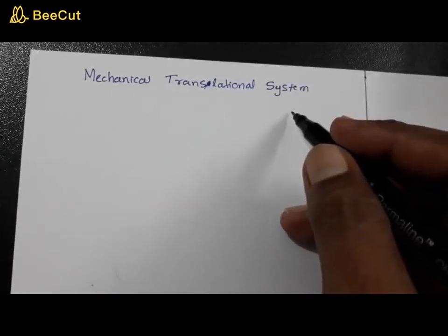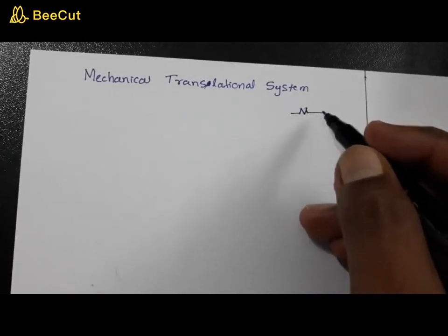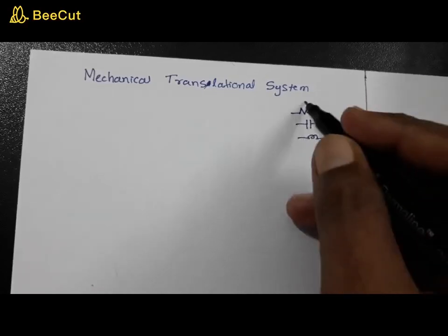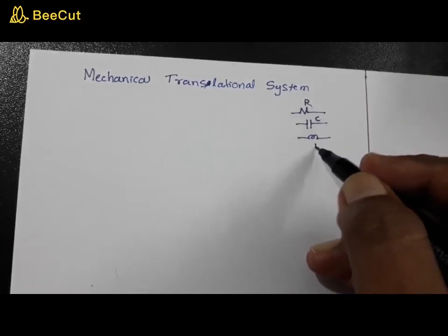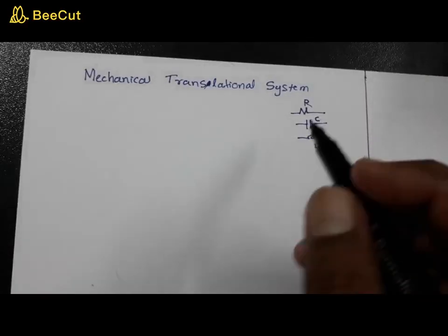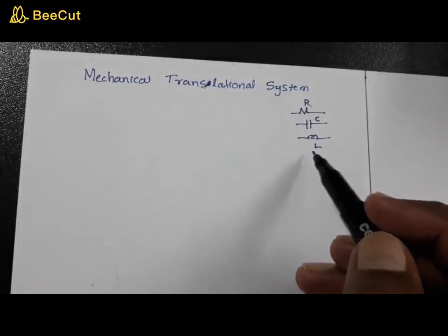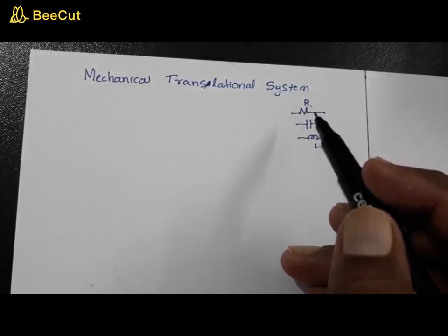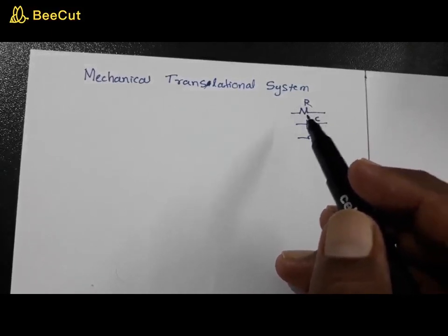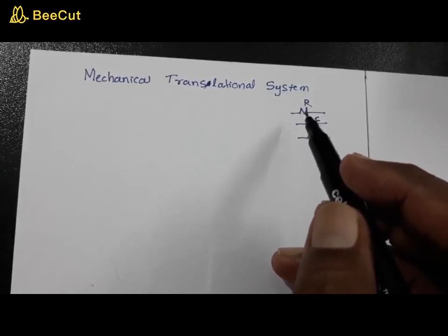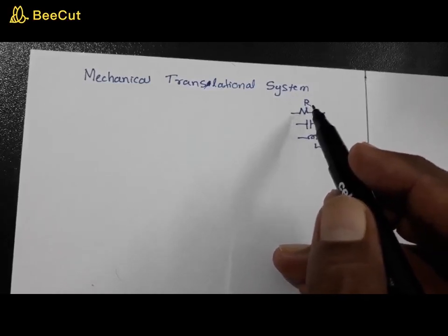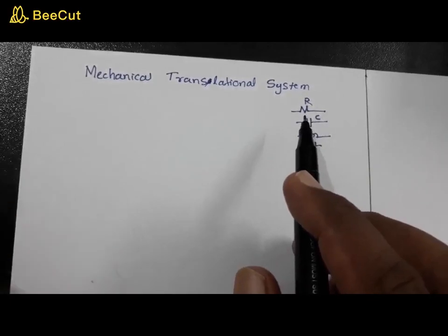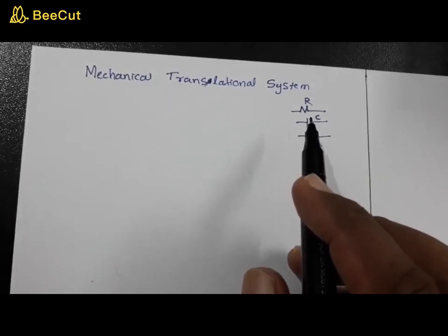Now, we have studied that in an electrical system you have three components: resistance, capacitance, and inductance. By these components an electrical system is formed, right? And we know how to find the transfer function. Modeling refers to finding the transfer function. First of all, the first step is to identify the output and the input, and get as many equations from the network by applying KCL and KVL.